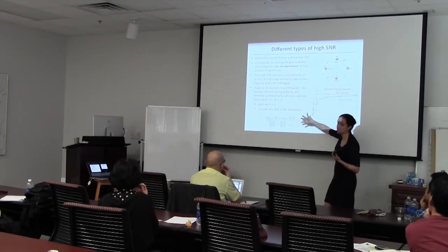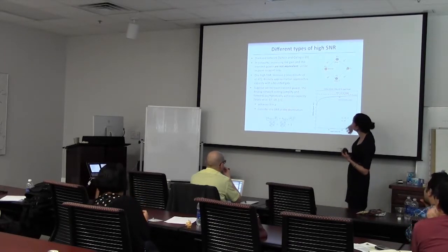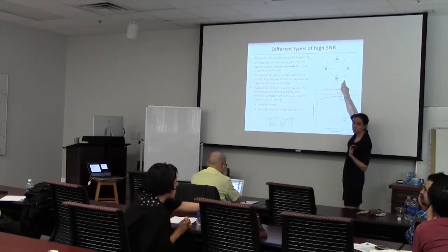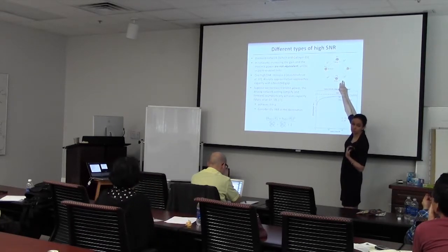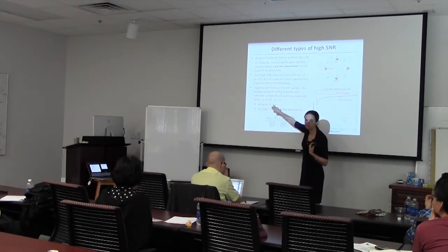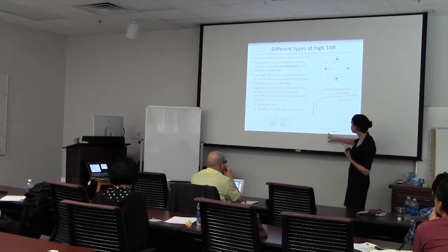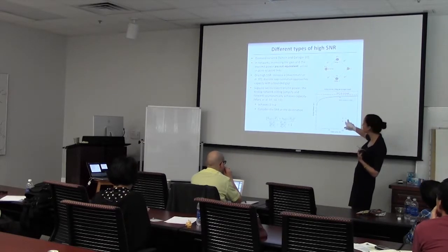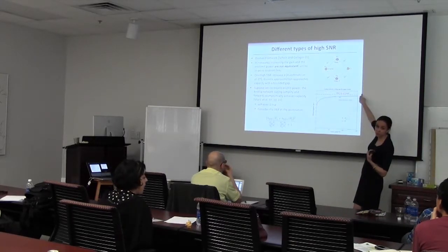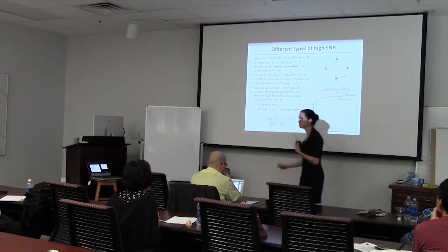Okay, so this is just the SNR at the destination, and if you plug in these A squares and A cubes and so on and so forth, what you'll see is that the dominant effect is going to be the A cubed. So I'm going to take A cubed squared, and I get 1/2 log of A to the 6th, so it gives me 3 times log A. That's the usual sort of highest SNR min cut. And so as my source power goes up, if I keep these P1 and P2 fixed here at 1, and I keep my gain fixed here at 10, what you see is that this is the MAC cut set bound. So the multiple access channel at the destination is the cut set bound, and one is approaching the other.